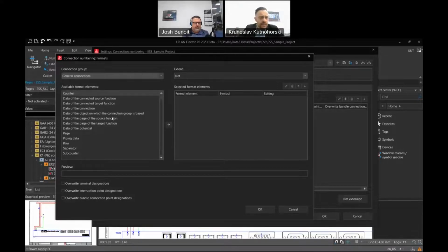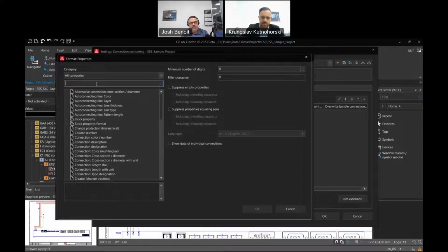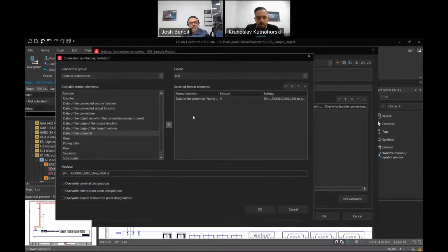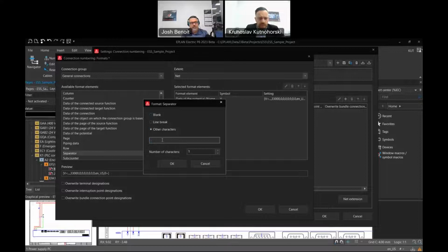In my case, because I had a customer yesterday who was interested in having the potential name and then a counter, I said, okay, it's very interesting. It's very easy. You can just set here data of potential, for instance, and you're searching for the potential. The software will find the name of the potential. Then we will add a separator. As you see, you can have blank, line break, or other characters. I will add here the underscore.